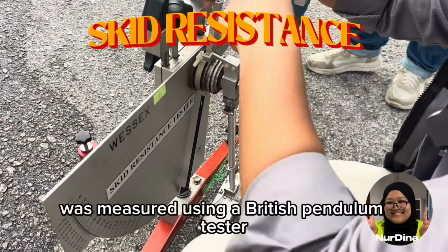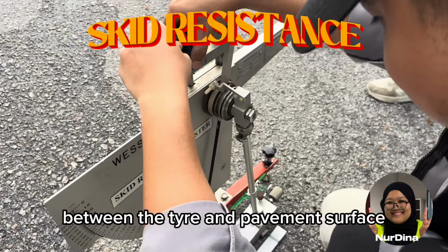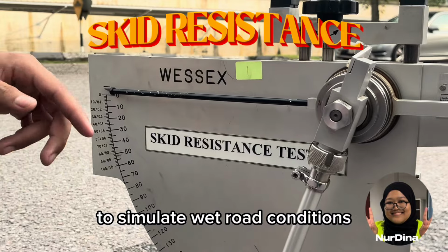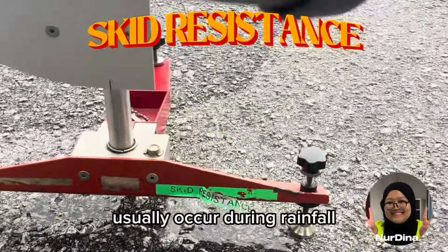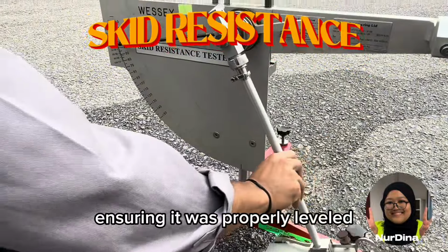Firstly, skid resistance was measured using a British pendulum tester, which is a standard apparatus commonly used to assess the frictional properties between the tyre and pavement surface. Before conducting the test, the pavement surface was cleaned and wetted to simulate wet road conditions. This is important because skid-related accidents usually occur during rainfall. The British pendulum tester was then carefully placed on the test locations, ensuring it was properly leveled.